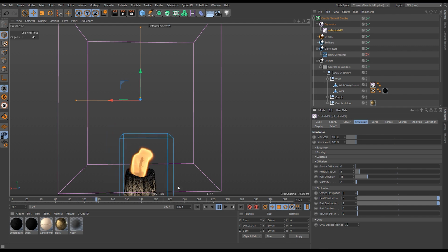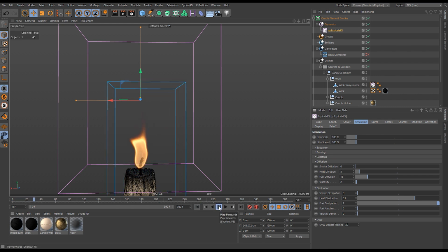This is unignited fuel, and therefore it's not burning. We're not getting any buoyancy, and it's not looking very realistic. So we're not going to dissipate it that much. In fact, we're going to dissipate it just below 1. So one unit of heat every second. A bit less than that is going to be removed from our voxels,